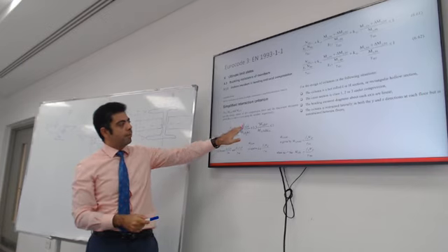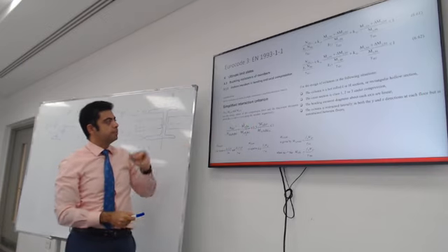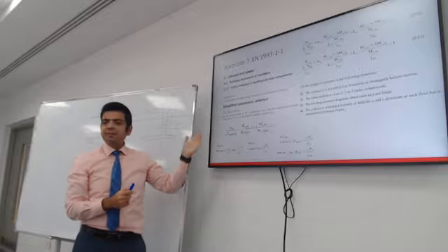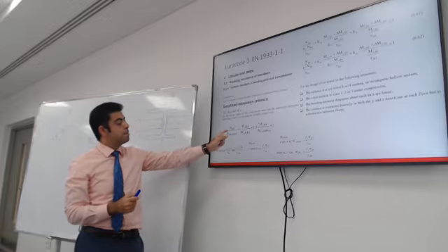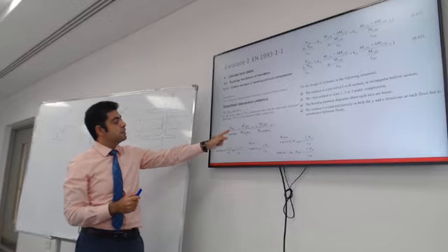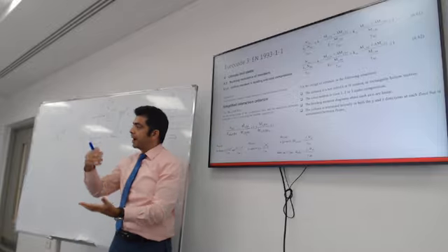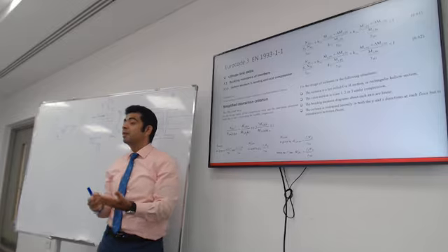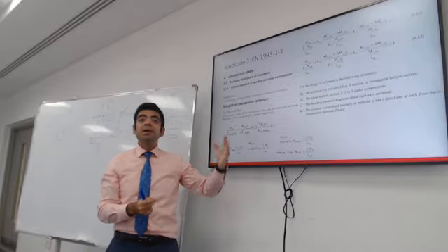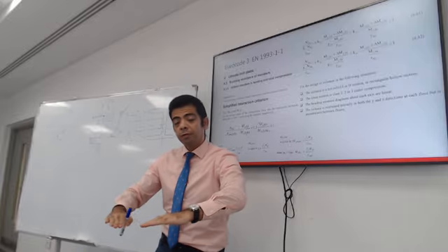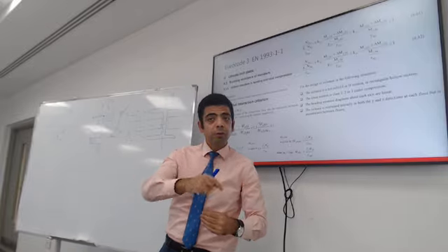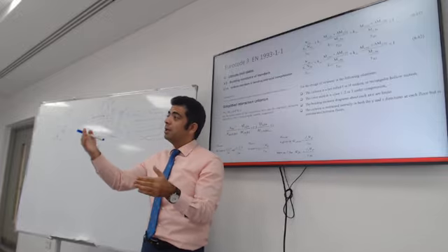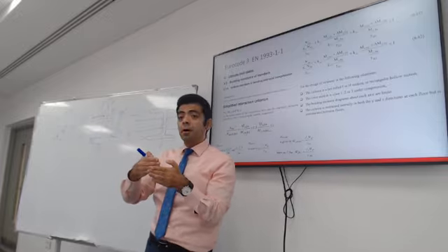What are the top factors here on the column? The Eurocode has this interesting symbols. E is the effect of the load. So you calculate the self-weight, you calculate the live load, and figure out the load on the floor, and then from the load on the floor to the load on the beams, and from the reactions on the beams, you get the axial load on the column.